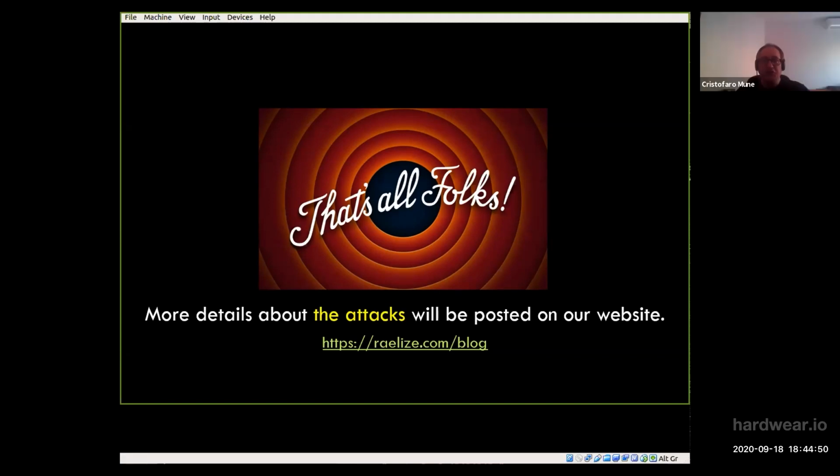Yeah, that is a very good question. It can happen that you have casualties in your process, that's for sure. Especially because of the power that you are exerting on the chip. You might have the impression that it is focalized in one place. It is not true, because the EM field, at least in our case, has a radial symmetry. So you're not necessarily glitching where the probe is.